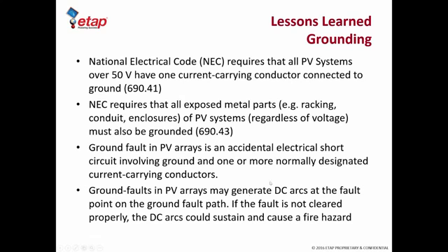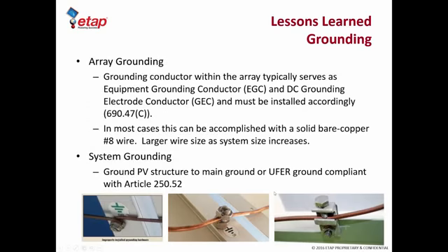But in cases where it has to be done during the day, because of some kind of fault in the system, and it's not possible to shut down the entire system, you may want to run this calculation and determine the appropriate PPE and label the equipment accordingly.